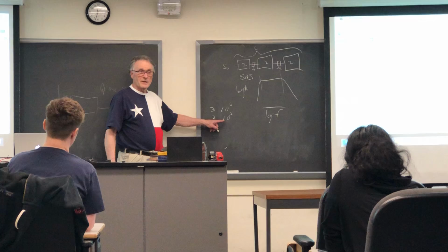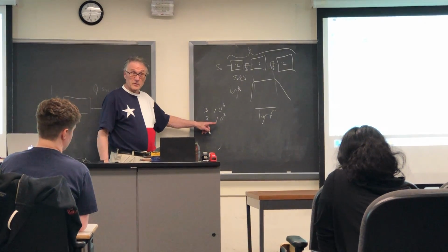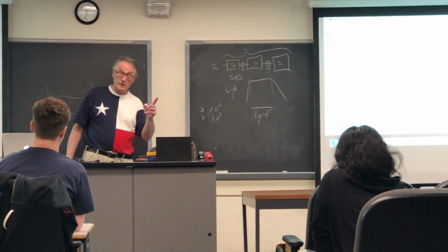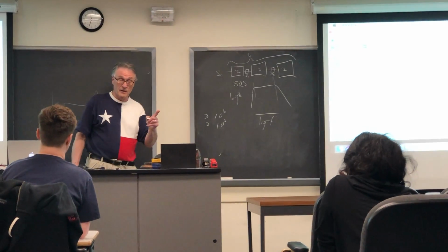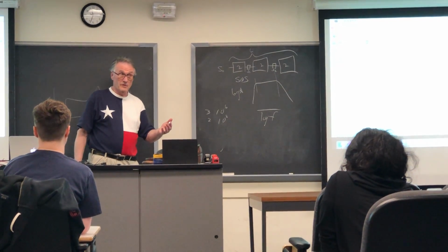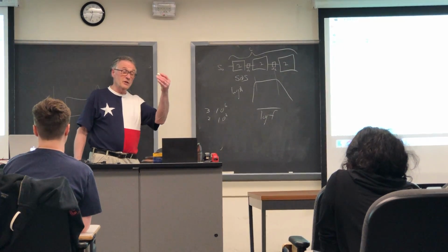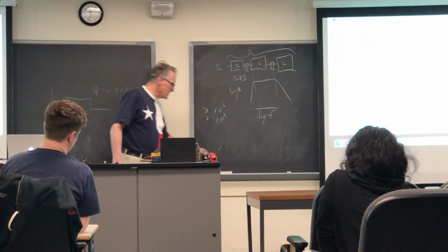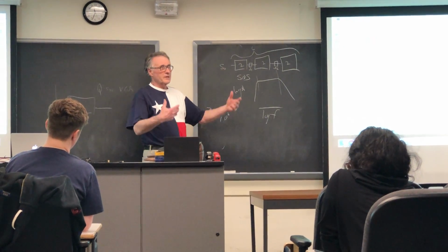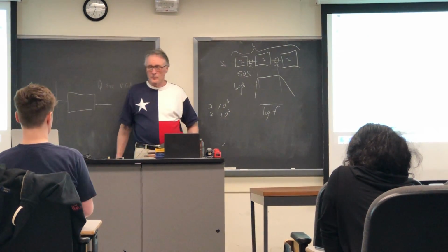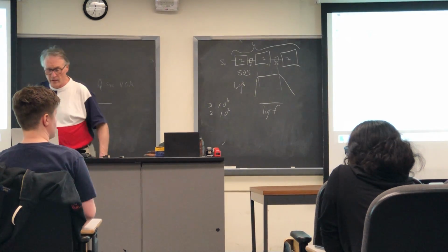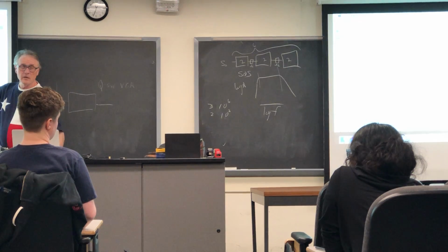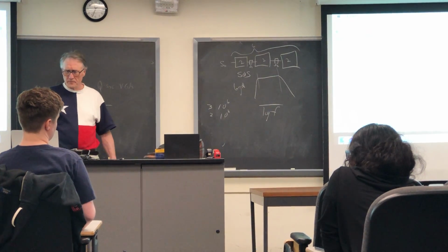Whenever I say normalize, I'm meaning shift here. So there's a big shift operation that has to be done at the input of the add. Then you have to do the add, which is trivial. And then you have to do a big shift to renormalize at the end of the add. So it's all the normalization stuff you have to do because of the exponent encoding that makes this such a big and slow process.